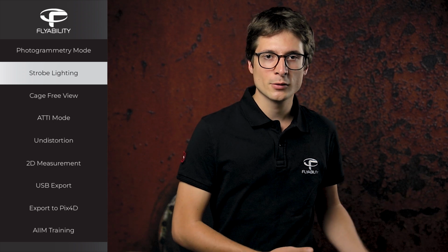The second feature we're introducing is the strobe lighting. When you activate the strobe lighting mode, the LEDs are synchronized with the camera shutter and produce pulses of light just when the camera shutter is open. The light pulses are 60% brighter, but the overall energy consumption decreases. As a result, the drone flies longer while delivering sharper images.